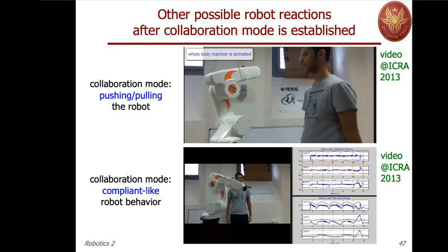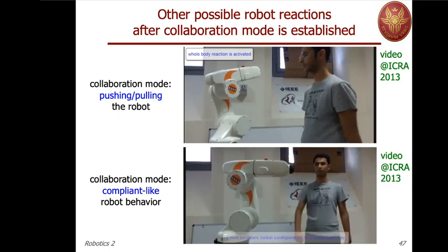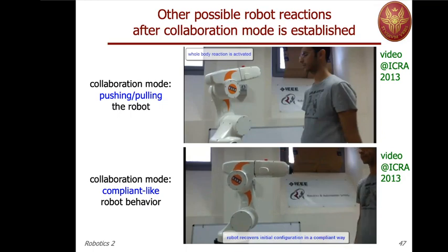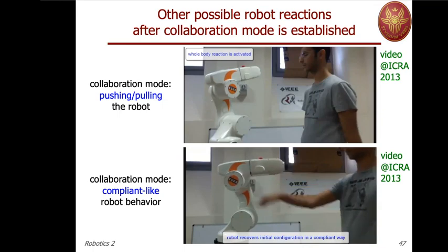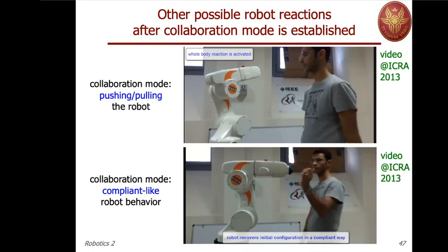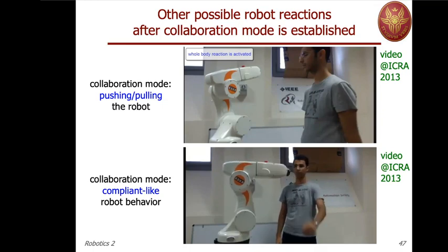So again, the robot will be stopped in a soft modality. You see that the motion is like having the reference position as 0 and then reacting like a spring in the various directions. But this would generate a torque, and we are not able to impose this torque, so we have to mimic it by a specially designed command at the joint velocity level.